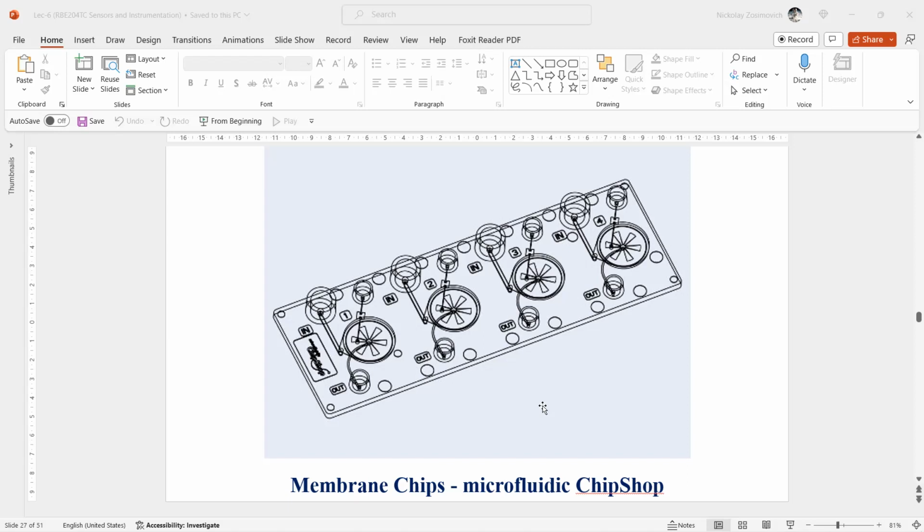The sensor is made up of two processed wafers put together face to face, resulting in a narrow gap between them. After bonding of the two wafers, the substrate of the top layer is removed by selective etching, leaving a thin membrane of near 2.5 micrometers.